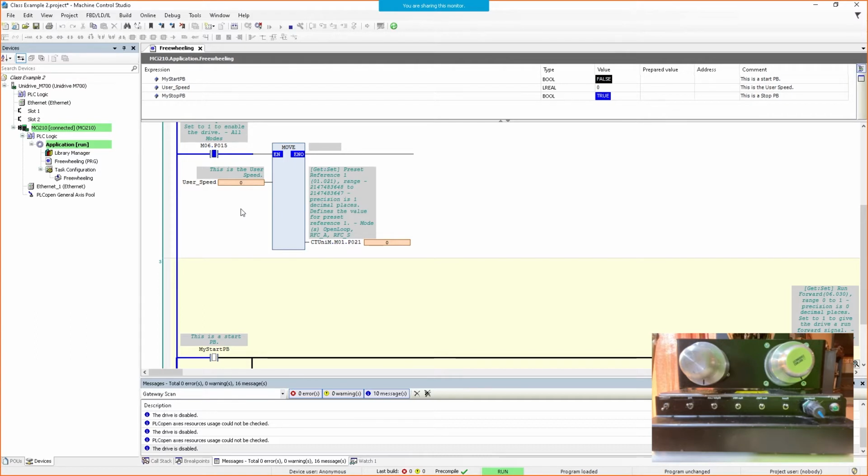This program will automatically start on power cycle of the drive, the host drive. So if you do a reset, or a trip on the drive were to occur, unless you initialize these to something real, and I do not recommend initializing to 0 either, particularly if you're using variables in mathematical formulas, you'll end up with a divide by 0.